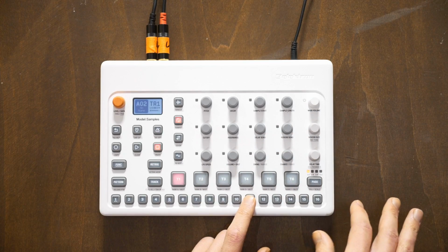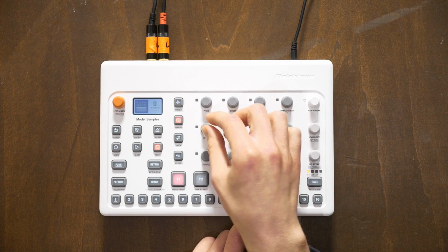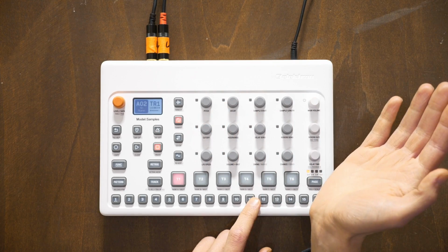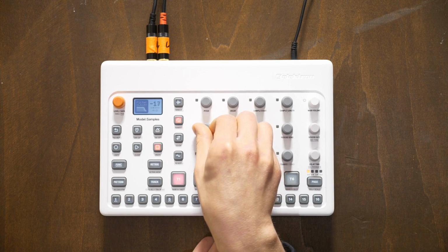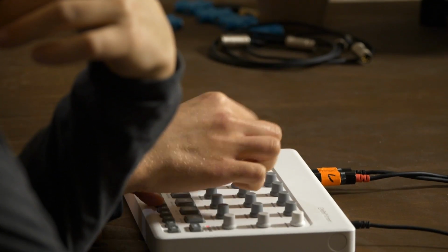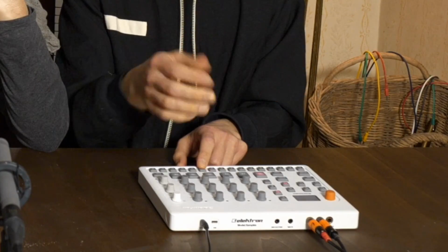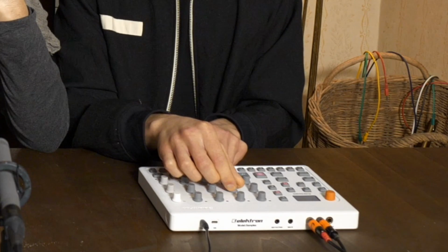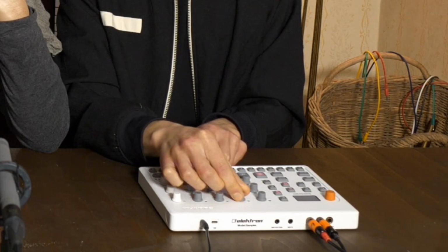And if we then also apply some filter. Since we have to move things around in terms of control, the cutoff is actually a mix between high pass and low pass. So if you turn it counterclockwise, it reduces harmonics, it's a low pass, and if you turn it clockwise, it starts taking away the lows. So if we make it really steep and add some resonance, we made a hi-hat.